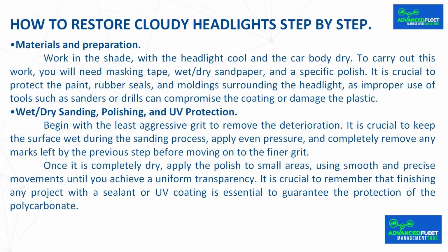Materials and preparation. Work in the shade, with the headlight cool and the car body dry. To carry out this work, you will need masking tape, wet, dry sandpaper, and a specific polish. It is crucial to protect the paint, rubber seals, and moldings surrounding the headlight, as improper use of tools such as sanders or drills can compromise the coating or damage the plastic.